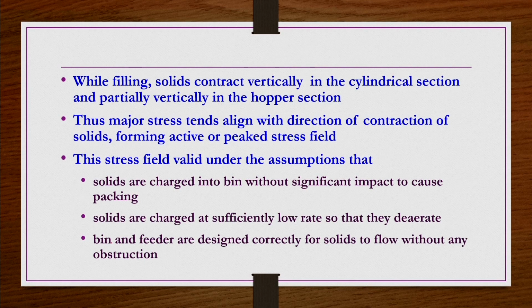This is very important. If the feeder and the bin are not properly designed, then we can have a kind of funnel flow, and things may be very different. Whatever stresses we are discussing are mostly valid for mass flow patterns, where free flowing of the material is taking place. If the bin and feeder are not properly designed, it is not possible to have a mass flow pattern, so you may experience a funnel flow pattern. Those kinds of things are absent as per this analysis. We are not considering those problems.